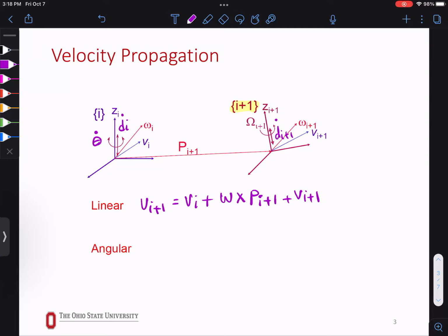This is kind of how you code it also. When you solve the robot, you ask how many joints do I have? User says 3. Okay, let's work. I'm going to write code that solves this for joints, and I'm just going to have a for loop and go between the joints: 0 to 1, 1 to 2, 2 to 3. This is a good method, called the explicit method, because you're basically writing your program, your code. You're using i plus 1, so it doesn't matter what joint it is. You just need to get from the user what kind of joint you're using.